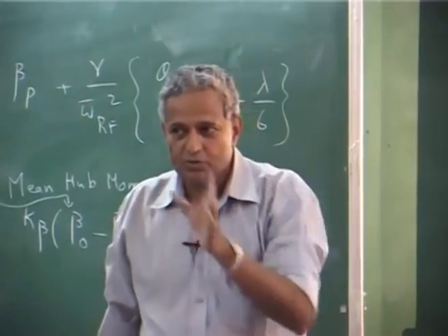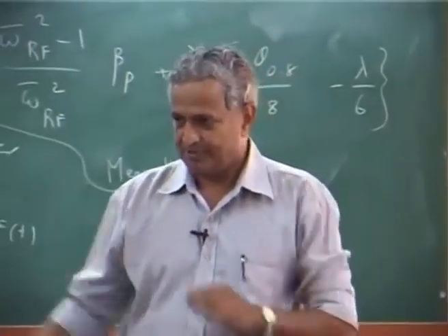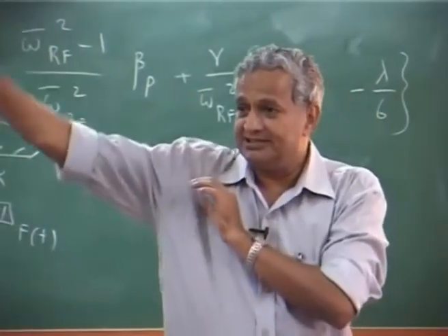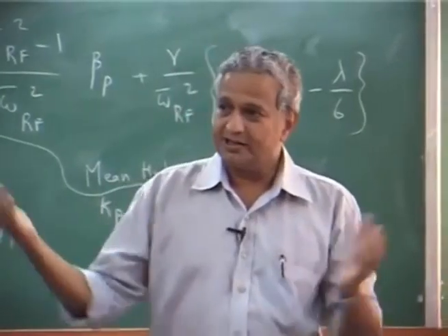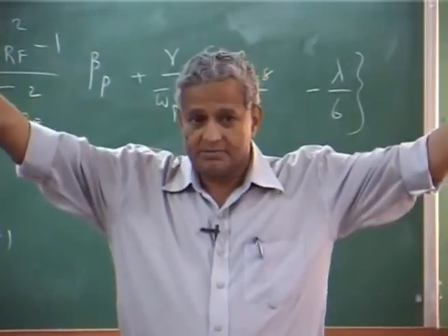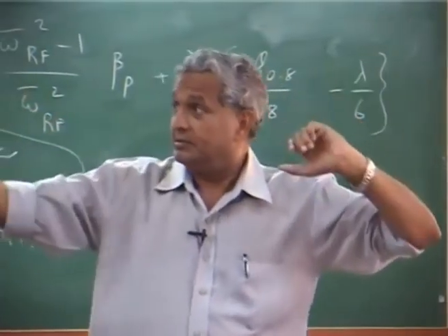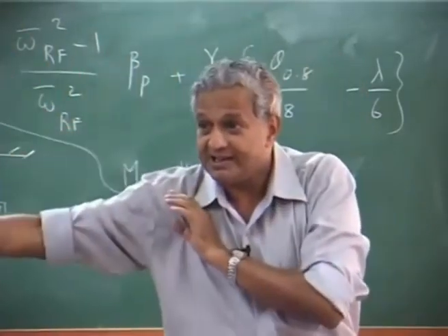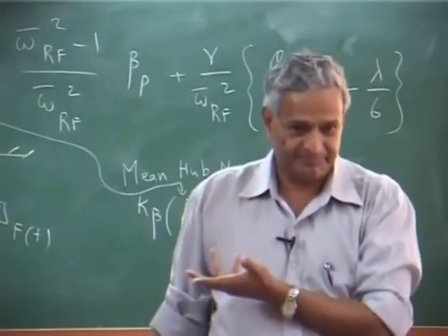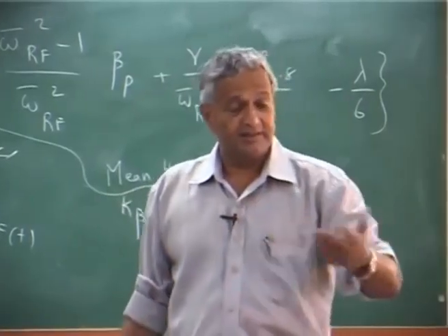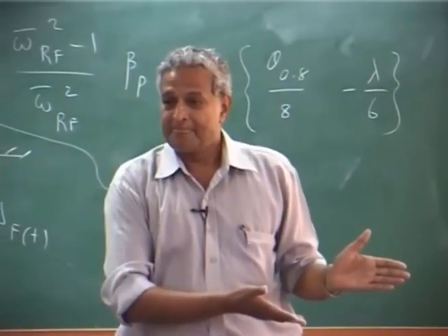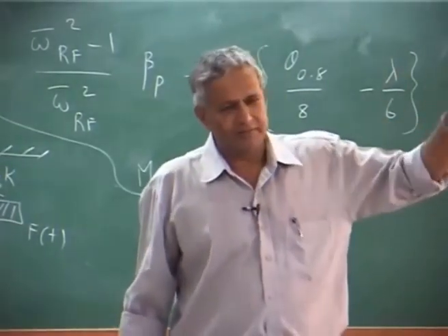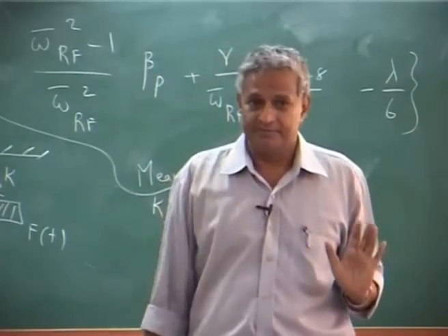So, that is why usually you do not look at flap deformation, because depending on the flight condition, it can come down, it can go up, anything, okay. If the coning is too much, that means your lift is very large, because that is why it is going up. If the coning is very less, it means my lift is less, okay. So, the coning angle changes with your weight condition, that is why all these are just to give some 2 degrees, you relieve the hub moment. It is purely from a structural design point of view, okay.